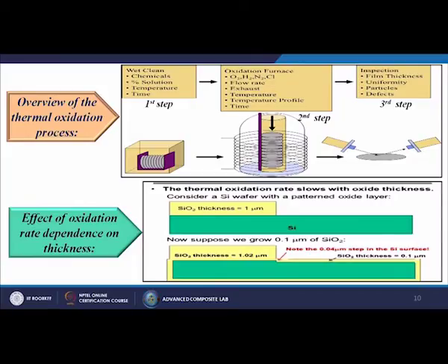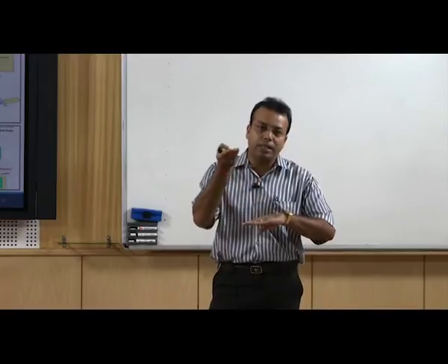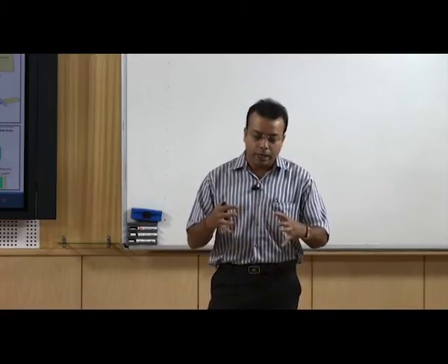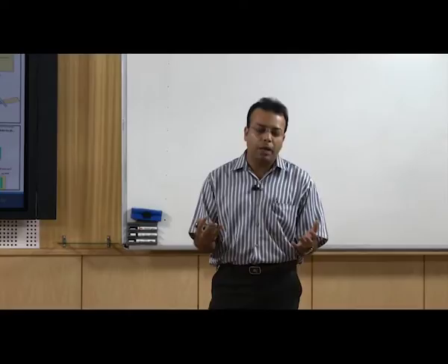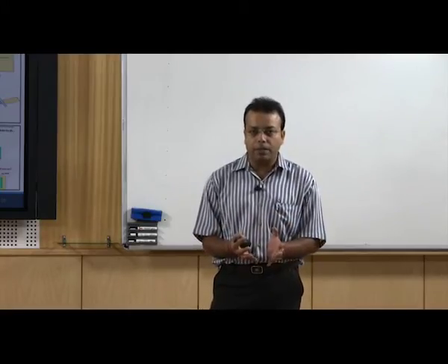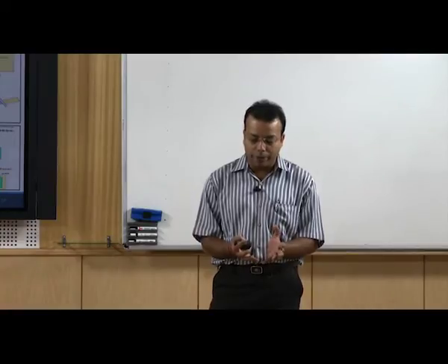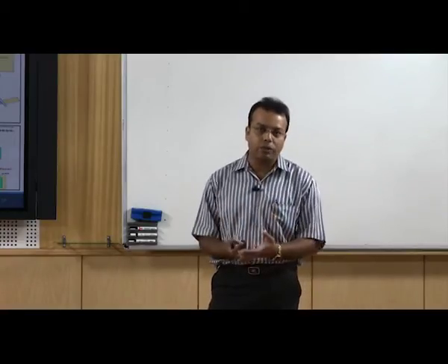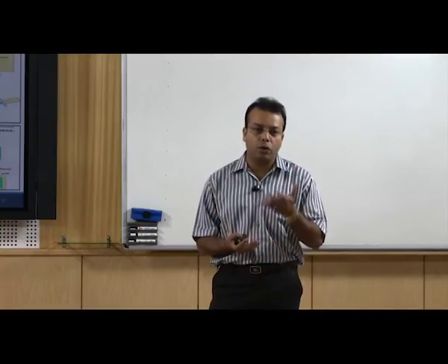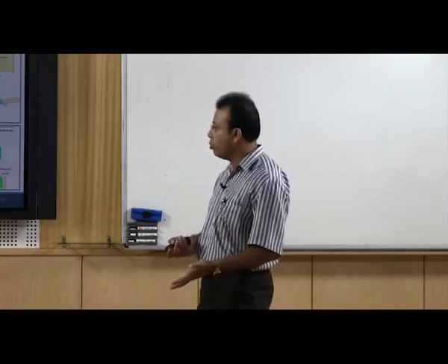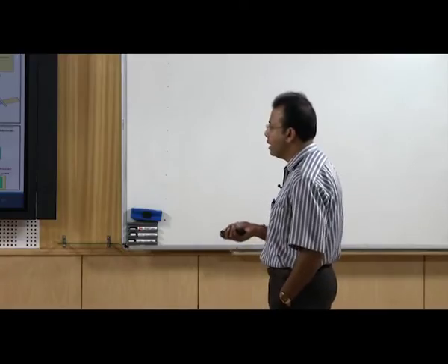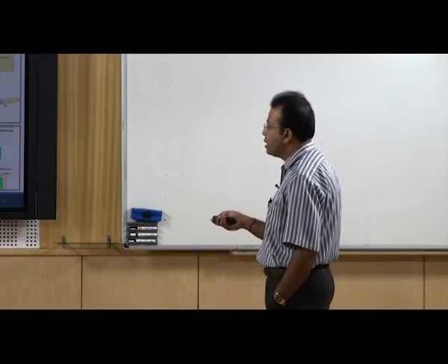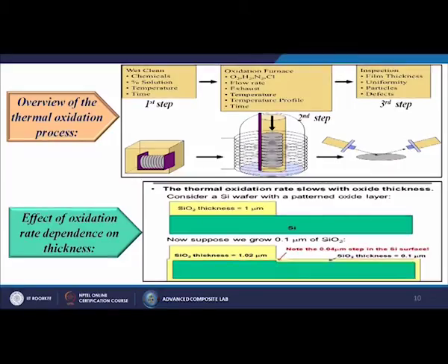So, as the oxide layer formation keeps increasing, by normal logic the silicon coming from the silane or the wafer, that quantity will be less. So, automatically the reaction will also be reduced. So, automatically the oxide formation will decrease. So, then the growth thickness will also be in a decreasing manner.